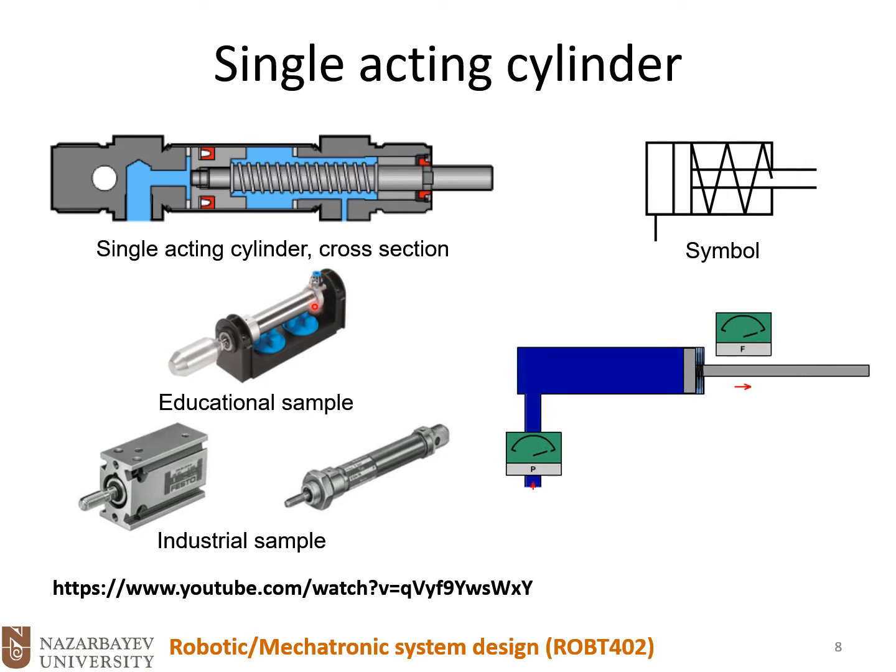Or what is the other way? Looking at the symbol. All pneumatic components have a symbol. Once we start working with the FluidSIM software, we need to work with symbols to make our circuit. So here you see the main port, plus the spring. So it's very clear that this specific cylinder is a single acting cylinder.